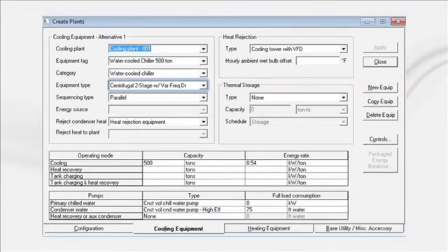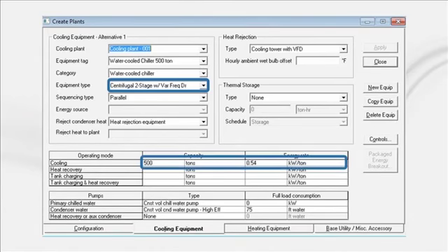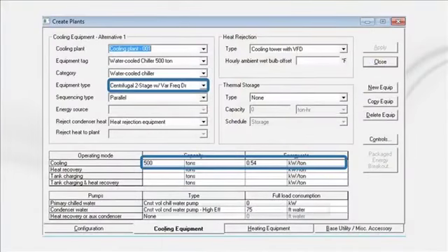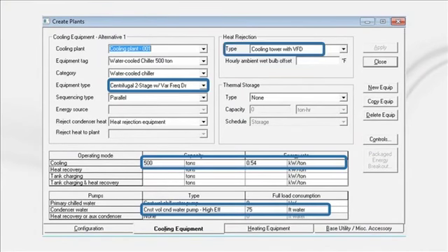In this case, we input 2 chillers with variable speed drives. Each is oversized at 500 tons and is high efficiency. For this, you can either select a library member or you can get input from the manufacturer and enter it. Entering the specific chiller takes a little longer. Next, there's a high-efficiency constant-speed condenser water pump with 75 feet of head and variable speed drives on the cooling towers.